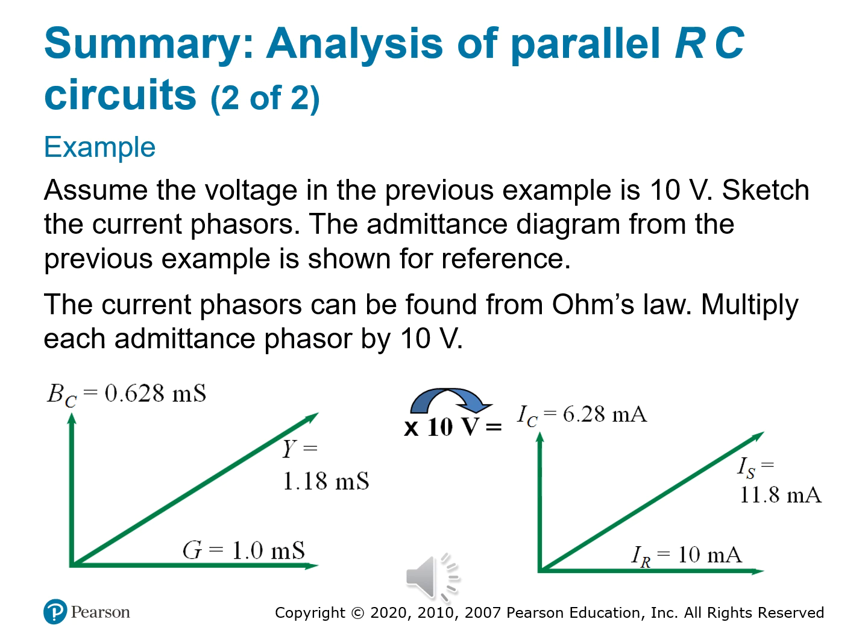But again, I sub R is always going to be on the positive real axis. That's resistance, always in the real axis, just like G. I sub C points up along the positive y-axis, so it's going to be a plus j, remember that? Reflecting the capacitive behavior. And the total current, I sub S, is the diagonal, that vector sum.